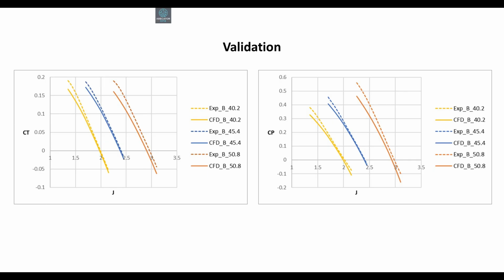The discrepancy between the experimental and the simulation results appears as an offset or an effective shift in the blade pitch angle. In some NASA reports, this variation in blade pitch angle has been attributed to structural deformation effects. You can now carry out the verification study on your own.